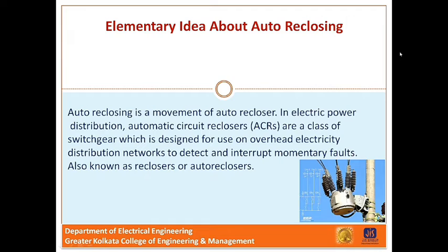Transient faults are commonly caused by lightning and temporary contact with foreign objects. The immediate tripping of one or more circuit breakers clears the faults. Subsequent re-energization of the line is usually successful. A small tree branch falling on the line could cause a semi-permanent fault. The cause of the fault would not be removed by the immediate tripping of the circuit, but could be burned away during a time-delayed trip. High voltage overhead lines in forest areas are prone to this type of fault, and it must be located and repaired before the supply can be restored.